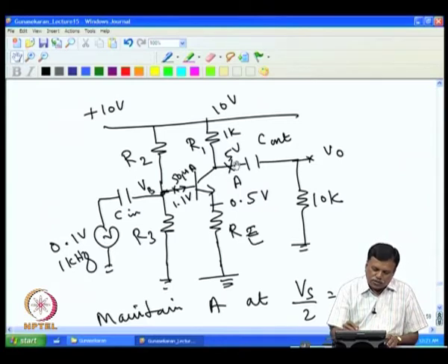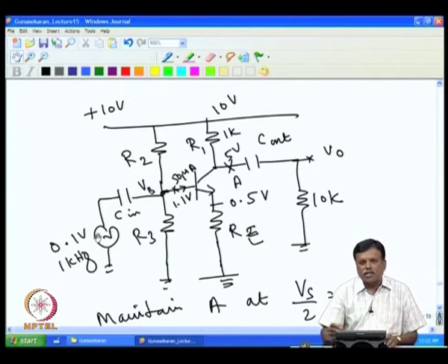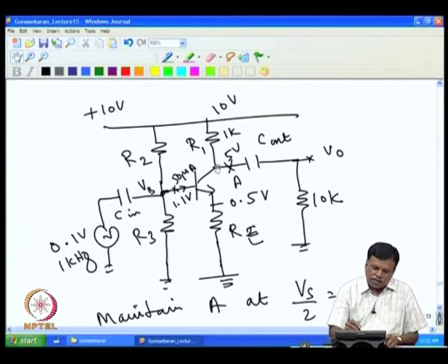Then when I try to go beyond that, you will have a problem, because maybe I will get a 2 volt swing or 3 volt swing maximum, I can expect, not beyond that. So, you can go at the maximum 0.3 volt here in this design. So, one can get different values of R1, Re, R2, R3 depending upon the supply voltage and the input voltage level that is expected, and of course, the load also plays a dominant role.